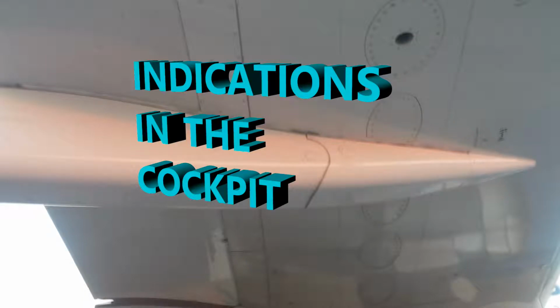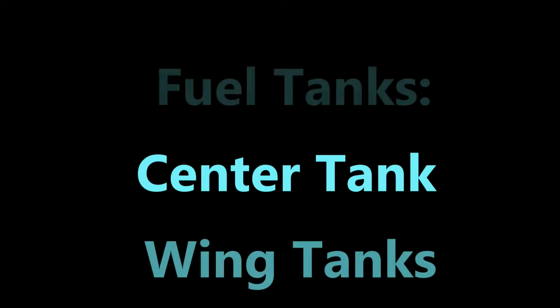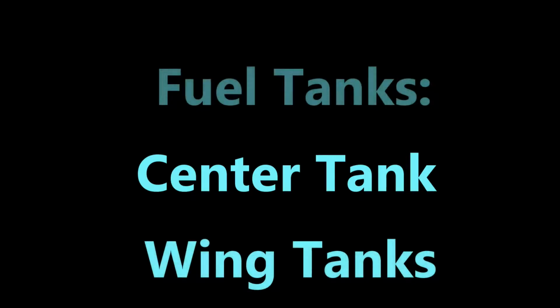Okay. So with the tanks, and remember I said there's 6, they're actually operated by pumps. So you have a pump for each tank. Now, the ones in the center, the two in the center tank, depend heavily on that pump. So if that pump fails for whatever reason, it's not going to be able to get that fuel distributed to the engines.